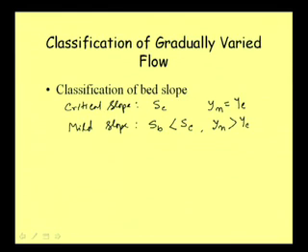Well, then we have a slope that we name as a steep slope. We did discuss this before also. Again, we are just refreshing that, and we are going into some of the finer details. Steep slope means when our bed slope is greater than the critical slope, meaning steeper than critical slope, and then we call that a steep slope.